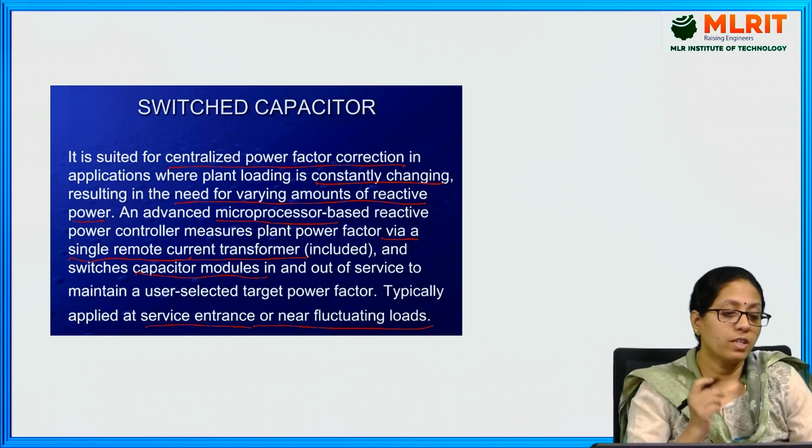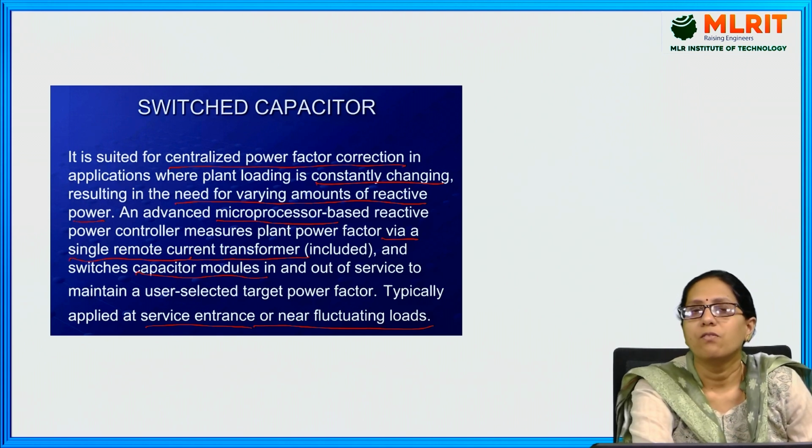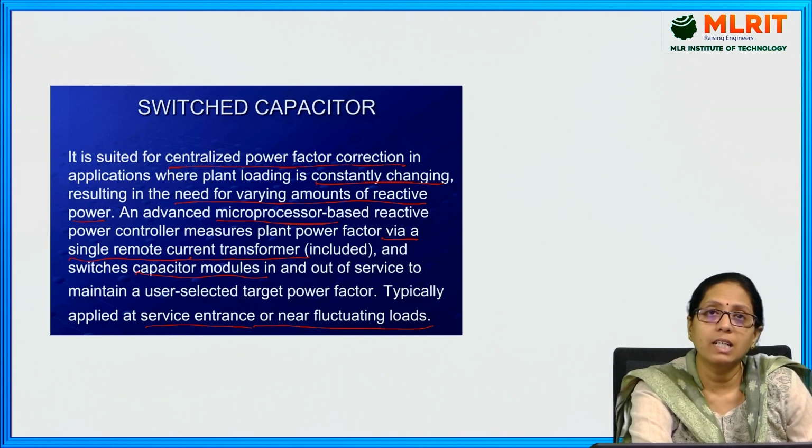That means for fixed load, we will be connecting the fixed capacitor. For variable loads, we will be connecting the switched capacitors near the plant.